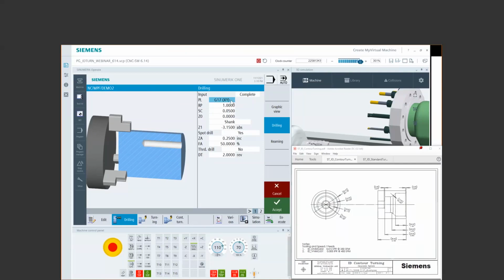There was a question about diameter mode off. You do not have to shut diameter mode off because in this case, I'm just sending it to 0. So that's okay. If I was live tool drilling, then I probably would turn diameter mode off so I could position radially. But I can just keep diameter mode on. Just remember that my X locations would be relative to that.